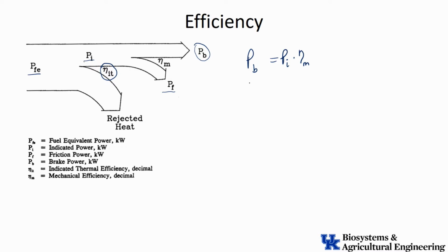Likewise, let's see, we're going to look at the indicated power, and how it relates to the fuel equivalent power. So the indicated power is the fuel equivalent power, so what's coming into the thing, times the indicated thermal efficiency. So those two relate together.